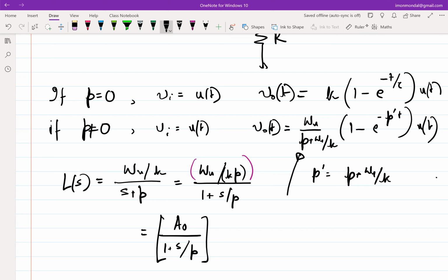Now, one disclaimer before we proceed. This unity gain bandwidth of the loop is omega U over K only for this particular configuration that we took: a resistor divider of factor K with an integrator in the loop and so on. But you might not have this configuration. You might have maybe a capacitor here, maybe a capacitor there, maybe another amplifier somewhere. So this expression of omega U over K will change. But whenever you plot loop gain, you will always find an omega where your loop gain crosses 0 dB, which is called the UGB of the loop.